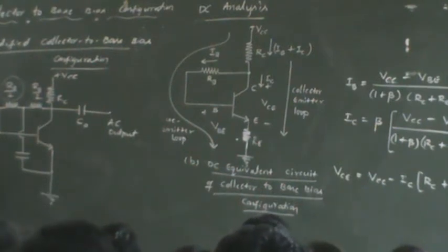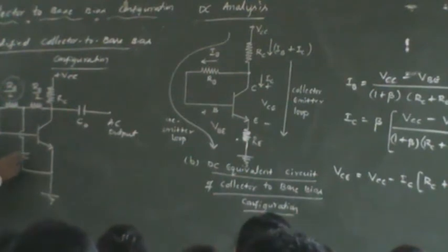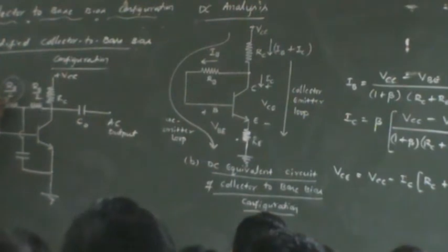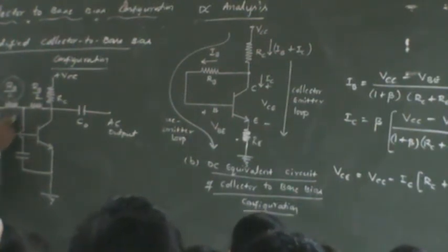But look at the feedback. What feedback are we going to experience here? Is it the same as the original circuit? Feedback is the same as this because for DC circuits, this will not come into the picture. But only for AC signal, this additional resistance will be included, because for AC signal this will act like a short circuit. Instead of current going through this, if some portion of current goes through this, RB by 2 will be the additional resistance. It's a bottleneck for us.